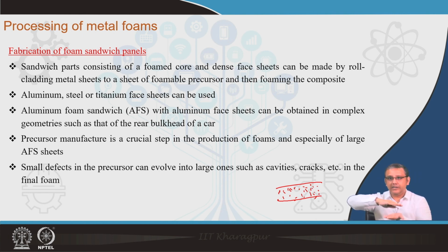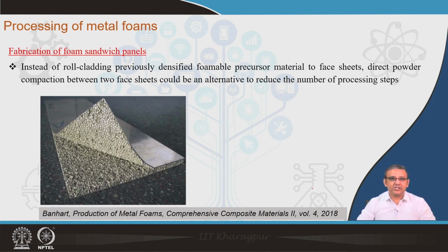Then this is bonded together by roll cladding and roll bonding, and if this is heated to a high temperature for foaming to occur, the titanium dihydride foaming agent will decompose, and that will form the pores inside the structure. Finally you obtain very unique structures where you can see that the outer surface is the solid face sheets, and inside you have a very nice and homogeneous pore morphology and structure, and these provide extremely good properties at a very low density.